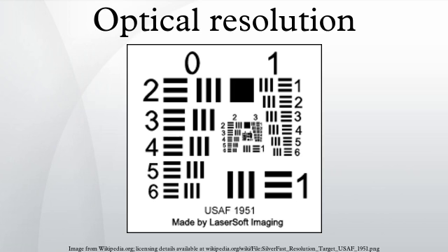Some modulation may be seen above the limiting resolution. These may be aliased and phase reversed. When using other methods, including the interferogram, sinusoid, and the edge in the ISO 12233 target, it is possible to compute the entire MTF curve. The response to the edge is similar to a step response, and the Fourier transform of the first difference of the step response yields the MTF.